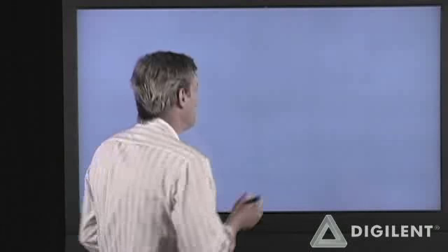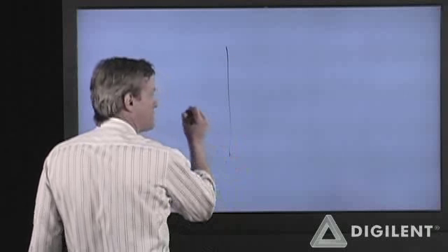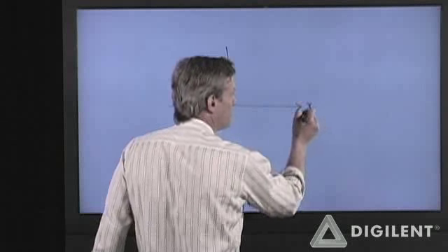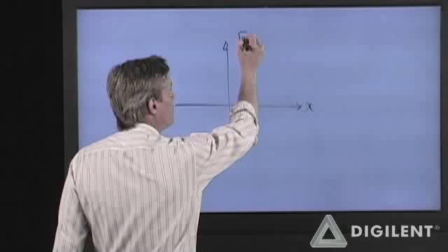Likewise, if I try to compress this spring, once I've compressed it to the point where there is no air gap between the coils, I have to apply a huge amount of force if I want to try to compress this anymore. The metal actually has to deform in order to compress it. If I plot this stuff graphically, this plots the same parameters that I used before, displacement and force.